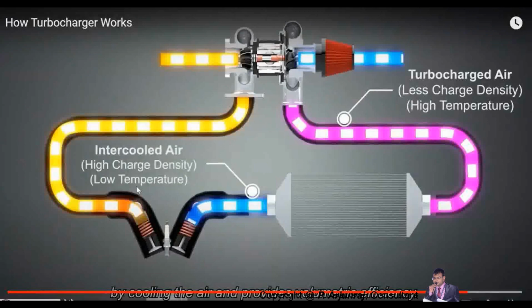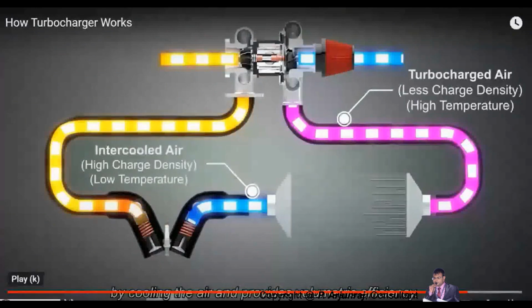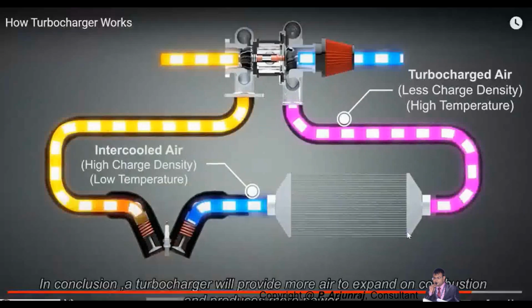But there are a lot of other problems that the supercharger also has, because you need to take the power from the engine, which means 20% of your power gets lost, because to drive this you need to take the power from the engine. Engine output basically cranks up. That becomes a very difficult task. And also you are going to put a lot of load on the engine. That is also a problem.